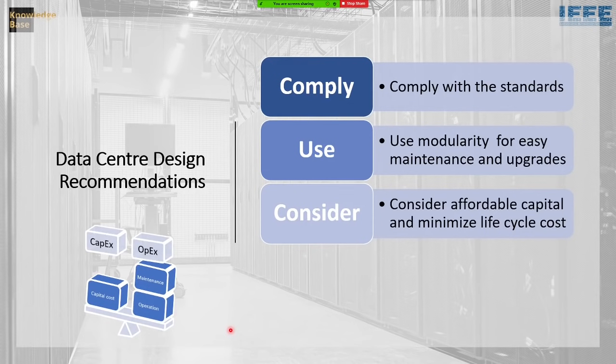So it's always important to find a balance between your capex and opex from a design perspective, because the way you design your data center reflects on the efficiency of the operation. Even selecting the location. If you design a data center and place it in the desert where it's 50 degrees outside, or you place it in Switzerland, let's say, where the temperatures outside are in the zero range, the one in Switzerland will be more efficient because you can use air from outside to cool your data center. But many things are considered.